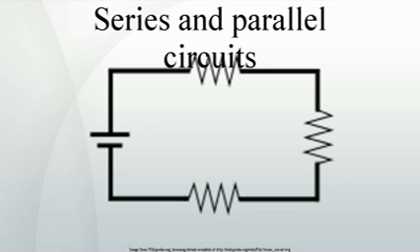The first 3 terms represent the sum of the self-inductances of the various coils. The formula is easily extended to any number of series coils with mutual coupling. The method can be used to find the self-inductance of large coils of wire of any cross-sectional shape by computing the sum of the mutual inductance of each turn of wire in the coil with every other turn, since in such a coil all turns are in series.